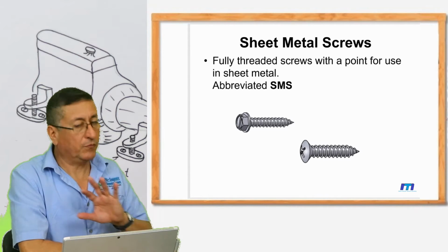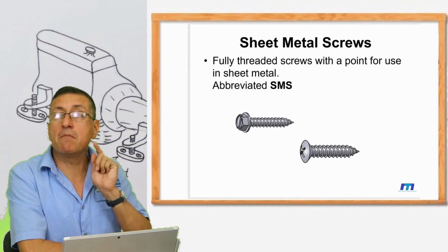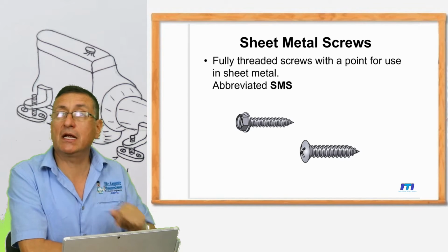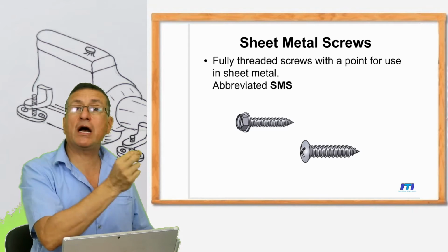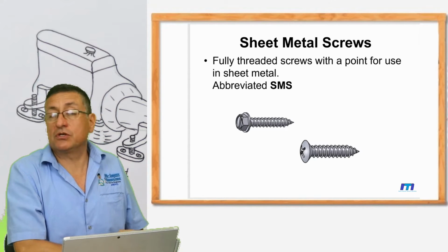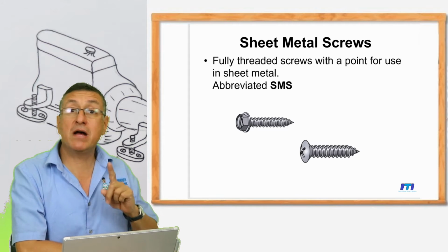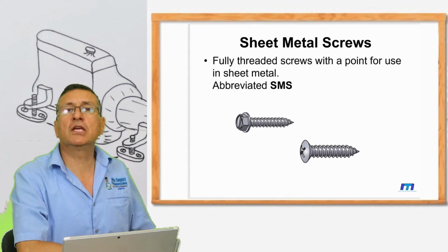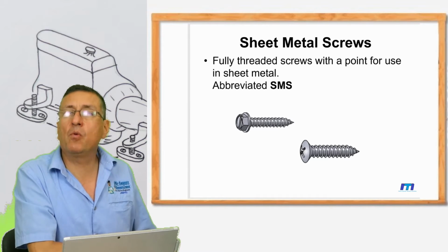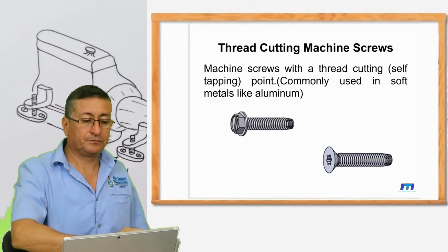Yeah, be careful. We can use those if the material is marine material. You approximate the magnet, and if the magnet does not attract the screw, it's because the screw is good stainless steel. The magnet is the secret. All right, be careful. Keep a good magnet in your pocket in order to verify the quality of those screws.